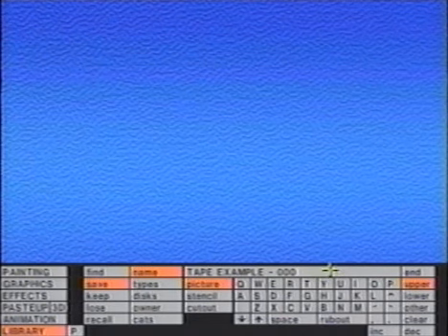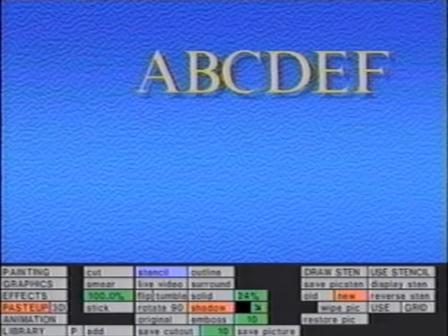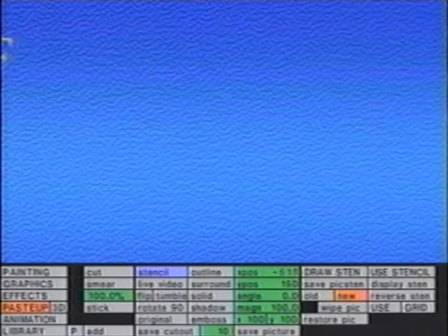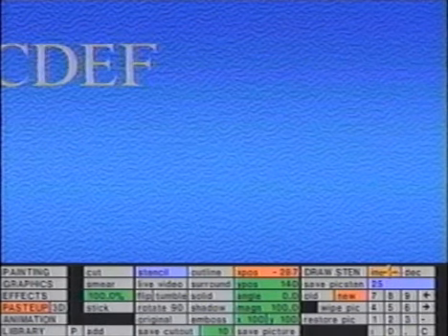Now for accurate working, we need to calculate by how much the text needs to move in successive frames. So the X and Y position numbers are noted at the start and at the end positions. Divide their difference by the number of frames required for the animation. In this case, we'll elect to simply move the text along the X-axis and increment its position by 25 units for each frame. Note that this method would allow us to change any set of statistics.